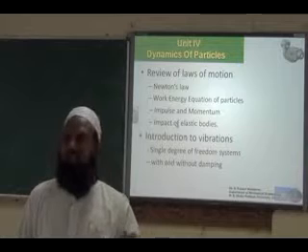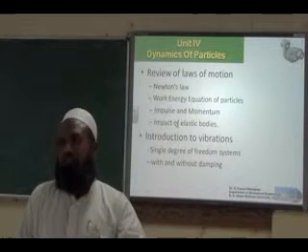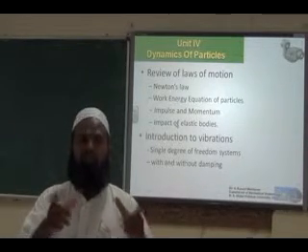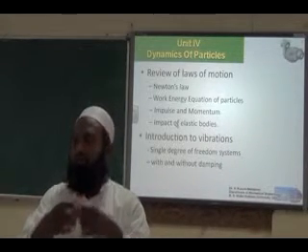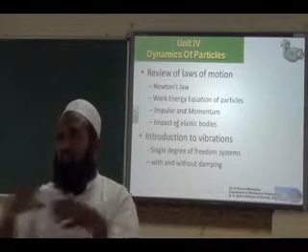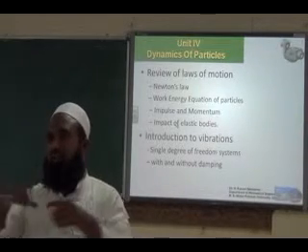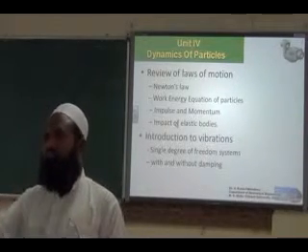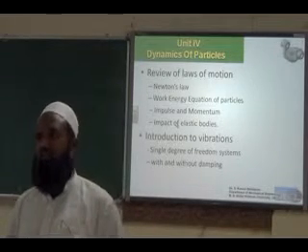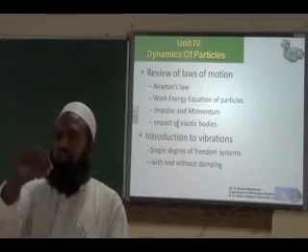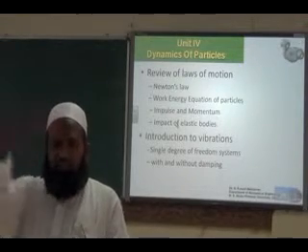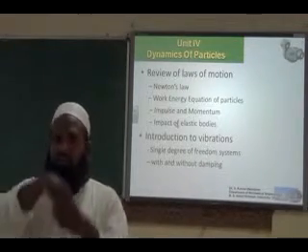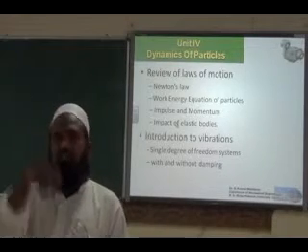That orientation can be done by using the sorting machine. The sorting machine will be vibrating, and there will be a hole which allows only a particular dimension. The horizontal dimension has a length and breadth. Breadth is smaller, length is larger, that we know. So it cannot insert through the length, it can insert only through the breadth. Like that, it will vibrate so that the workpiece will go vertically downward and get seated in the machine, and it will be drilled.